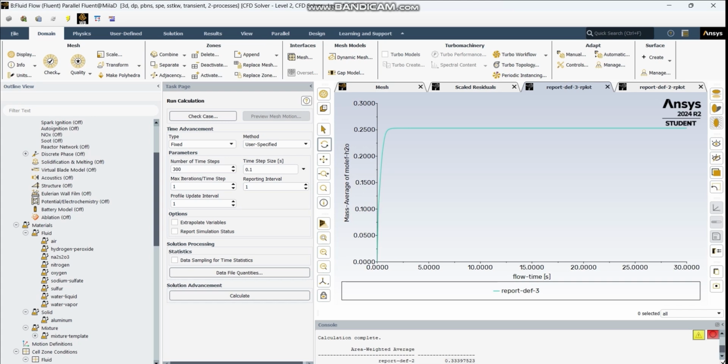On hydrodynamic uniformity, the impeller motion creates circulation loops and vortex structures. With the higher rotation, the flow patterns are much stronger, and the dead zones are minimized. This ensures that all regions of the tank are involved in the reaction, improving overall performance.